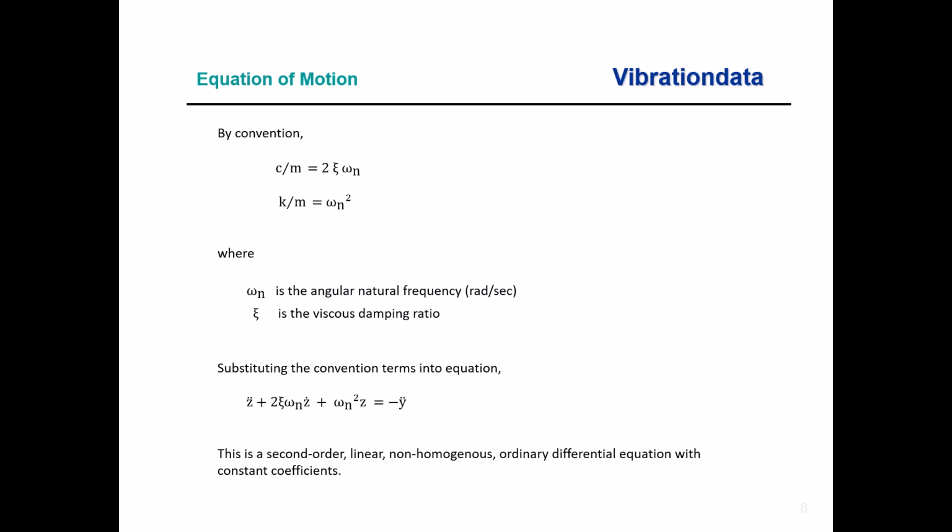Now we can also do an analytical prediction of angular natural frequency, but there's no analytical prediction for damping. That's got to be measured. So natural frequency is measured or analyzed by a model, maybe a finite element model or spring mass model or some sort of model. And then damping, you're on your own to measure that, although there are statistical databases to draw from.